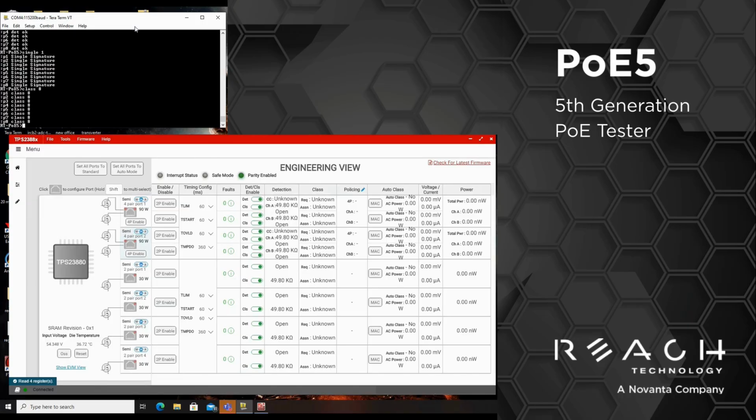You can specify load in either watts or milliamps. A lot of people find watts to be a little more convenient. But if you're trying to find the edge of where your PSC does a load cutoff, milliamps is a lot of times easier, because there's not the power noise where the load is servoing around looking for watts. It's a little easier to sneak up on things.